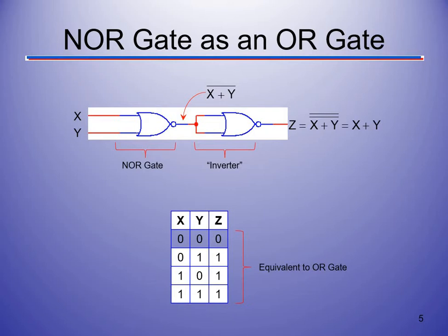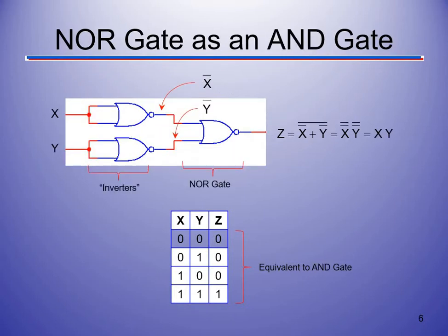Okay, so we use these 2 gates, and we're going to do the circuit replacement like we did with NAND. We use these 2 gates as NORs, and we can write them as an OR gate. Lastly, we're going to use NORs to write them as an AND gate.